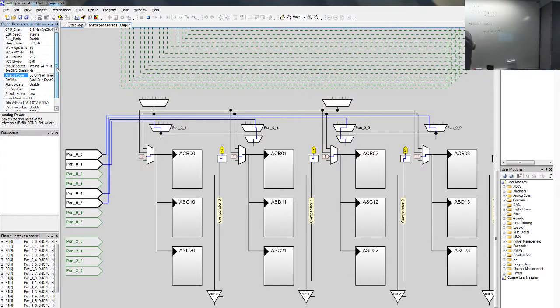And the analog circuits are designed for bipolar signals, so how you basically make a dual-sided power supply: you define plus V here and minus V here. Both are positive, and then you have the virtual reference ground somewhere. And those are the settings for the analog parts. Okay, good.